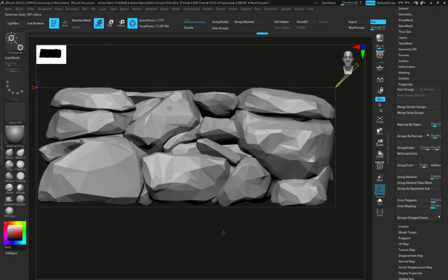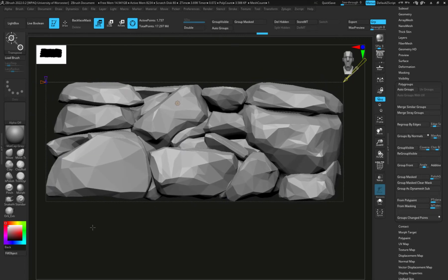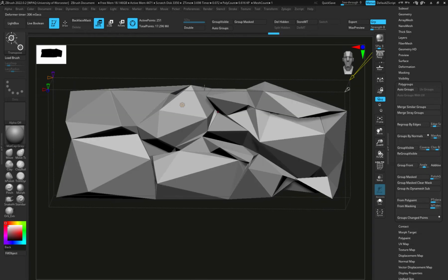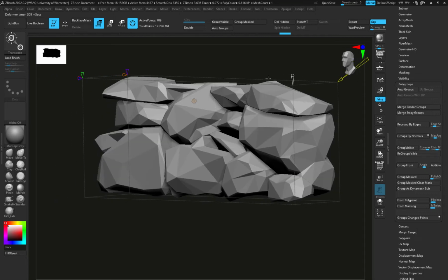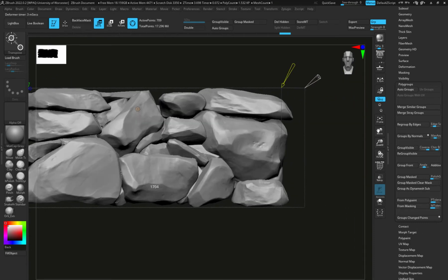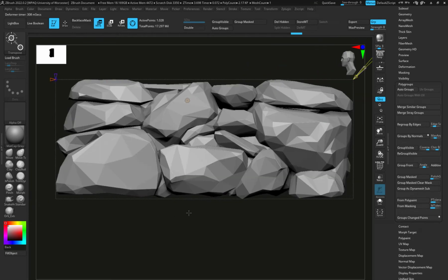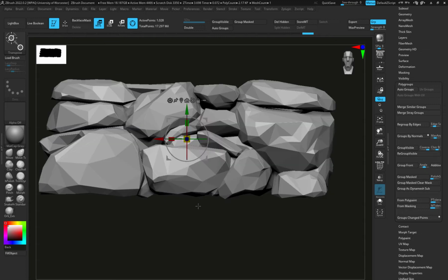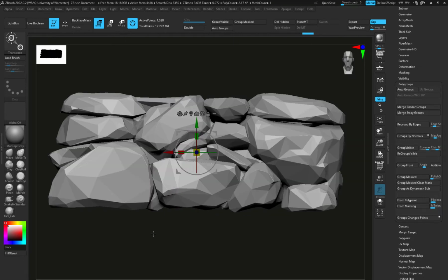And then we'll soften all these edges out as well. And we'll reduce it even more still. Okay, so I might just reduce that. No. Okay, I'm going to leave it at like 2,000, I think, and then I'm going to hit the gear, and then just accept, and then I've got that, which is going to be my low poly attempt from here, so we can try and customize and work with this to create a bit of a cleaner mesh, clean geometry, and see what we can produce.